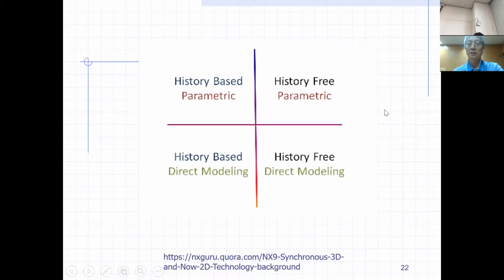So this is the same as feature recognition. As I told you, in the commercial world, the designer and manufacturer are many times separated. Even though the design is done by history-based and feature-based modeling, so there is history inside the CAD model, the model information is many times not handed over to the manufacturers.